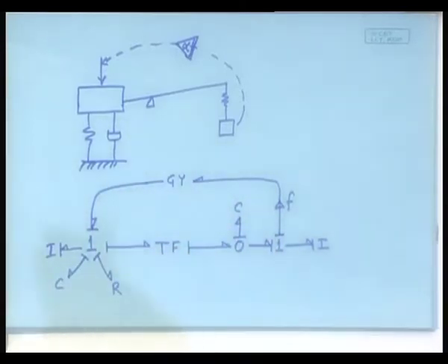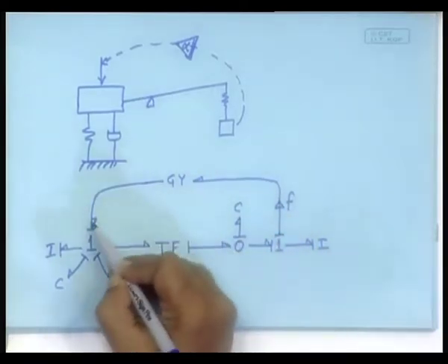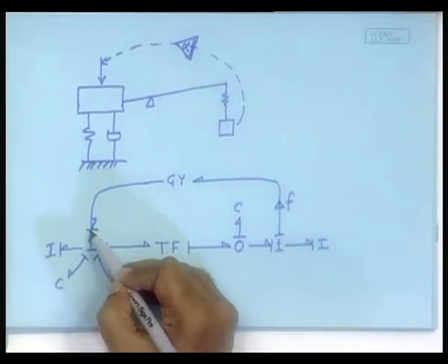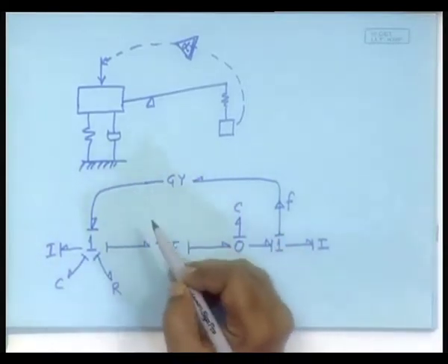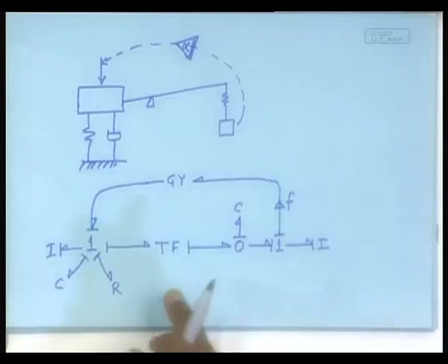One more important thing to consider is that even though this particular bond is not carrying power, this particular bond is carrying power because it is applying the force. So, in this case this is not power conserving, that you have to keep in mind. Fine. Let us obtain the differential equations of this.